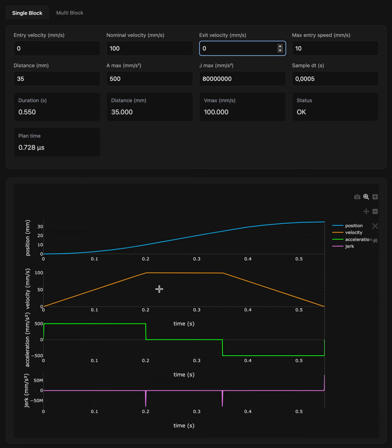And that's why I and others put so much effort into smooth linear advance and then axis smoothing for FT motion, so that even though extrusion is discontinuous, the extruder can cope with that because we make it artificially smooth. Well, the extruder won't skip, but we're still introducing errors, we're not doing exactly the planned extrusion, so there are still extrusion artifacts. And yes, you can print faster, and it looks okay, but it's not the optimal thing.